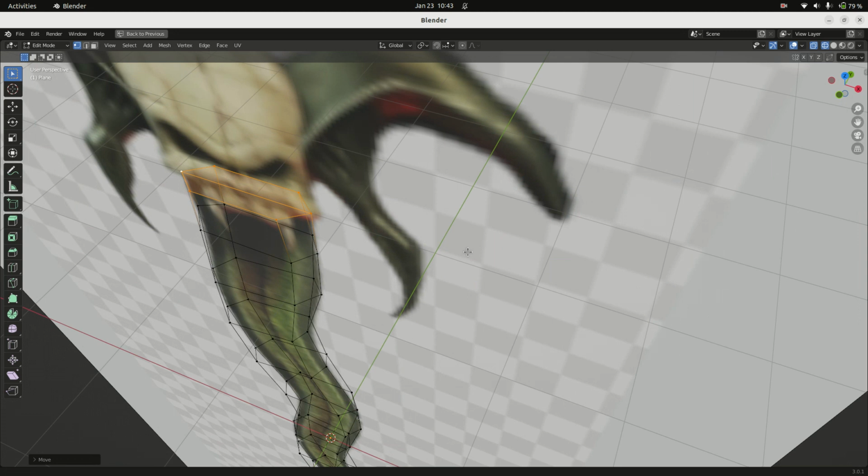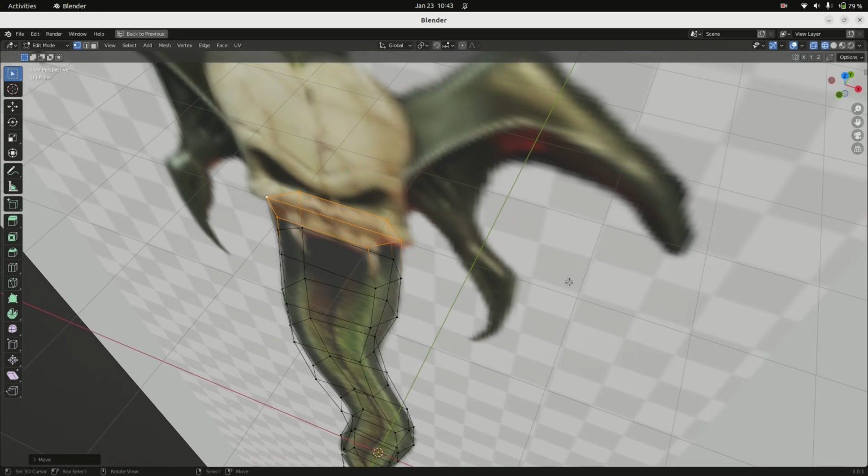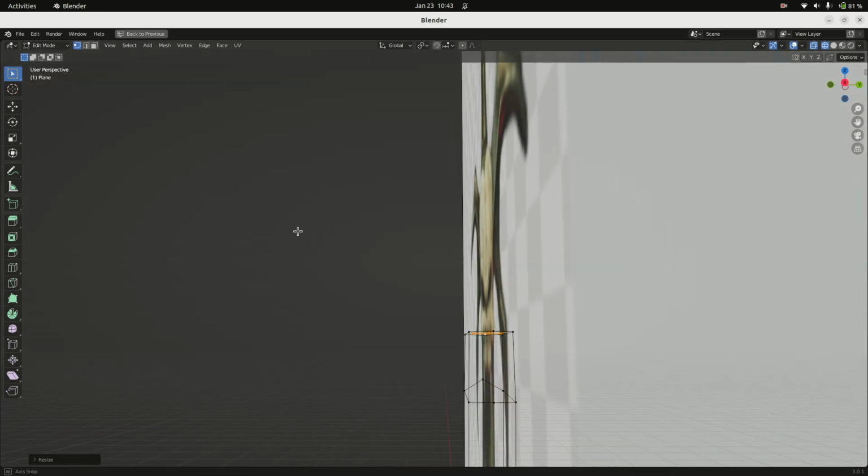Now here, let me show you how I can use the shape of a face that I have selected and use it to extrude new geometry. I'm going to extrude, but I'm not going to move it up and down. I'm going to cancel. And now what I want to do is scale it in place. Maybe scale it, this is the Y, a bit more here. And see how that is pulling the shape here, but it is still on the same plane. So I made that flat. It is all on the same plane.